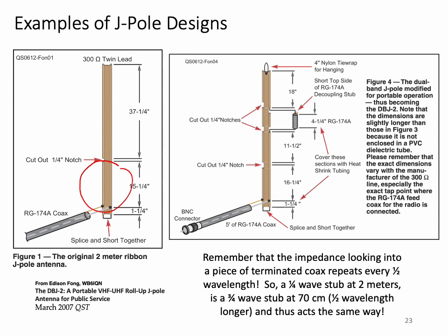In the dual band design on the right, we construct a half-wave antenna for 70 centimeters, and that's the 11.5-inch section right here. And again, we drive it from the base of that antenna. And we're driving it with a 3/4 wave stub, which is equivalent to a quarter wave stub on 2 meters and a 3/4 wave stub on 70 centimeters. Remember that those have exactly the same properties of converting the high impedance of the end-fed 70 centimeter half wave, for example, in this case, to the low impedance driving source.